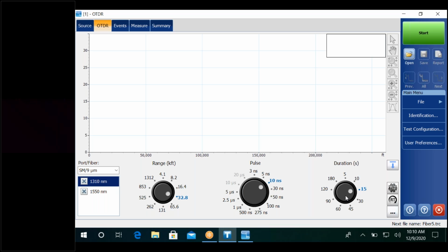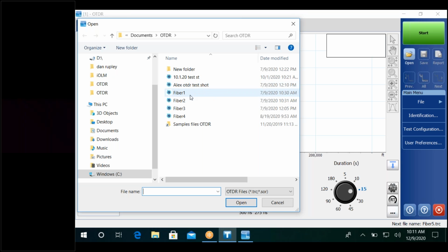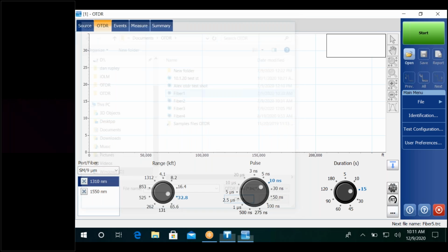Again, it's just what we knew. The OTDR application's perfect for troubleshooting. We got red lights on in the pop. Our equipment's alarming. We have a cut in the field. We're going to take that OTDR, we're going to plug it in, and it's going to immediately show us where our fault is. Great troubleshooting tool, necessary for characterization. Again, it's all we had. It's the eyes of our fiber. Lets us know the health of the fiber.